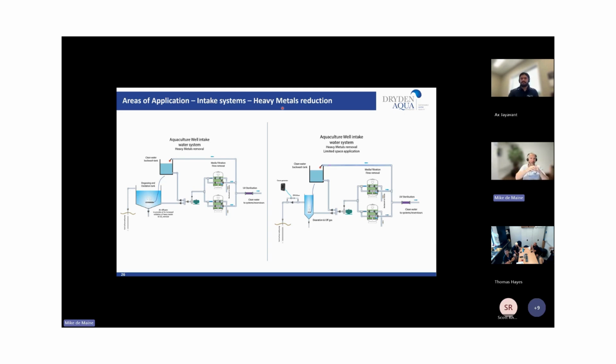When you go back into filtration, those clean areas above your laterals are the only areas that start to filter, which means that you think you're filtering at 20 meters per hour, but I've seen examples where those filters are filtering at 50 plus meters per hour, and fine, soft organics you cannot remove at those high velocities. So please have a watch of our webinar on filter design. It's very insightful.